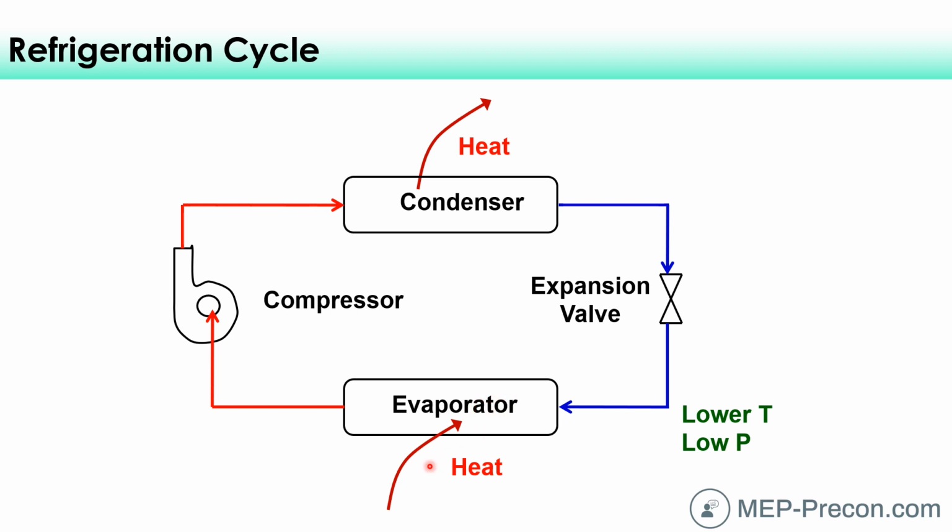So what's happening here is as we blow air through that indoor coil, we're going to circulate that supply air through here. It's going to go into our space, and it's going to return back at some temperature. And we're going to remove the heat from that by exchanging it with the colder refrigerant temperature.